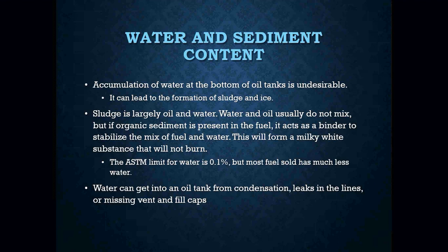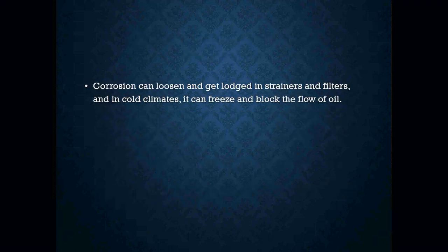So the ASTM limit for water is 0.1%, but most fuels sold have much less water in them. Water can get into oil tanks and your oil lines simply through condensation. It can come in through leaks in your lines. It can come in from missing vent and fill caps. Corrosion can loosen and get lodged in strainers and filters, and in cold climates water can freeze and block the flow of oil.